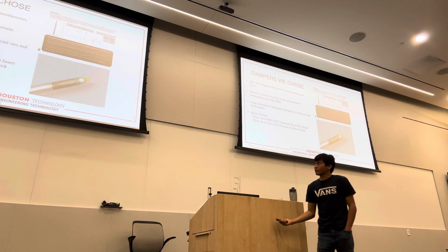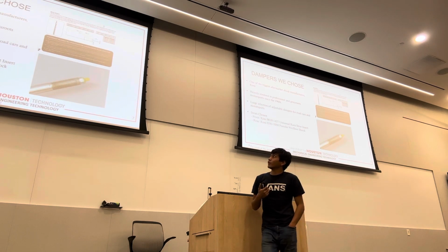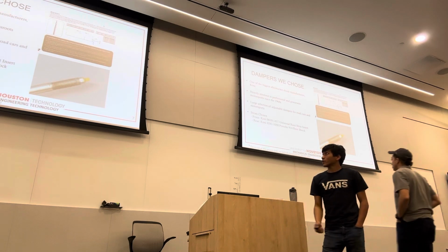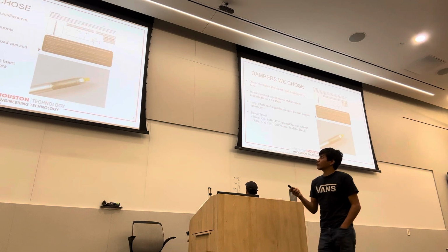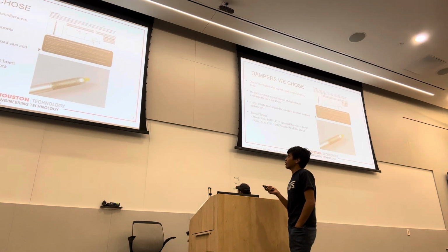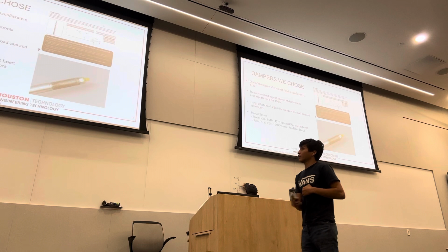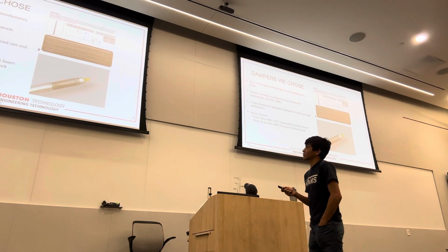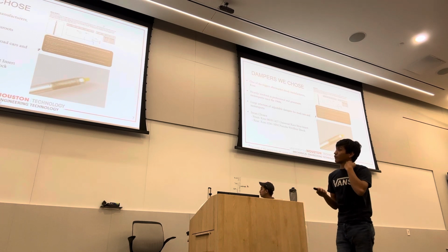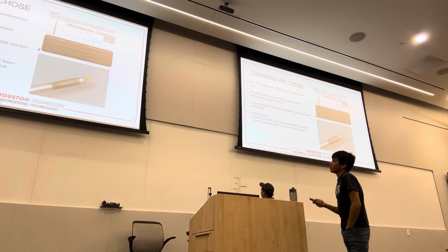So they're one of the biggest aftermarket shock manufacturers. They've been heavily involved in professional and grassroots motorsports since the 1960s. They have a large selection of dampers, and most importantly, they are adjustable via this knob at the top. So this is a very standard system they have for most of their shocks. Obviously this can change for some, but for the most part, this is constant. So we chose the front Koni Universal Racing Strip, and for the rear I chose a shock for a Porsche